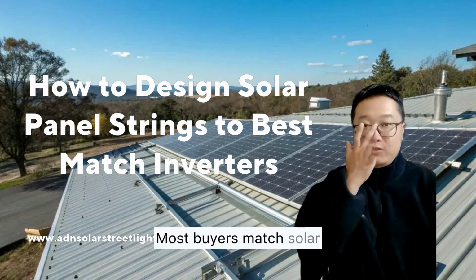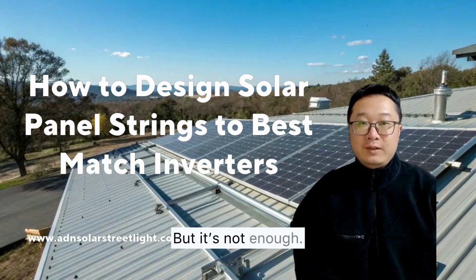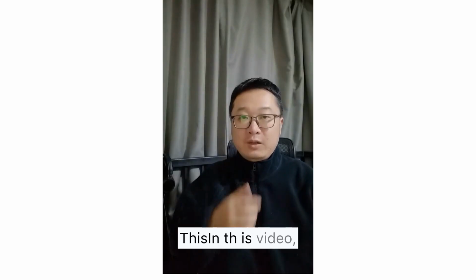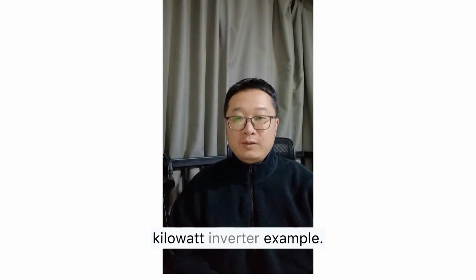Most buyers match solar panel power to inverter power. That's a fast start, but it's not enough. Good string design must also check voltage, temperature, MPPT range, and inverter limits. In this video, I'll show you how I do that, and why 16 modules per string is the practical target in this 420-watt module and 80-kilowatt inverter example.